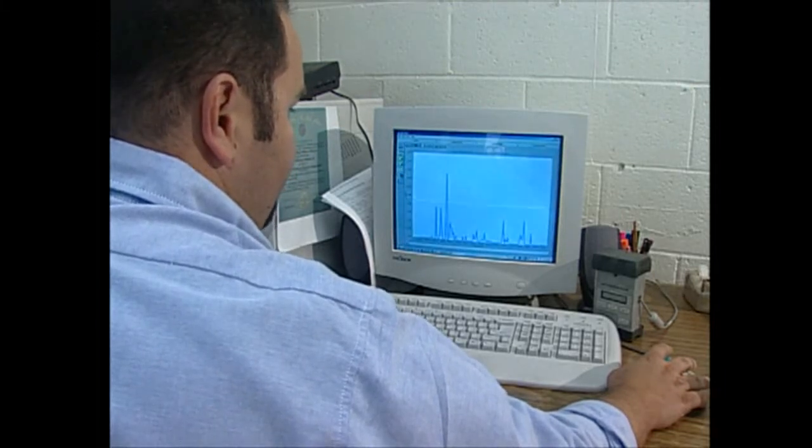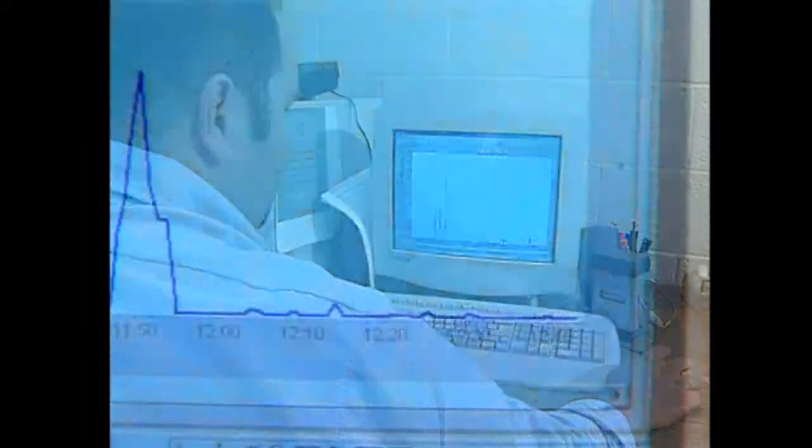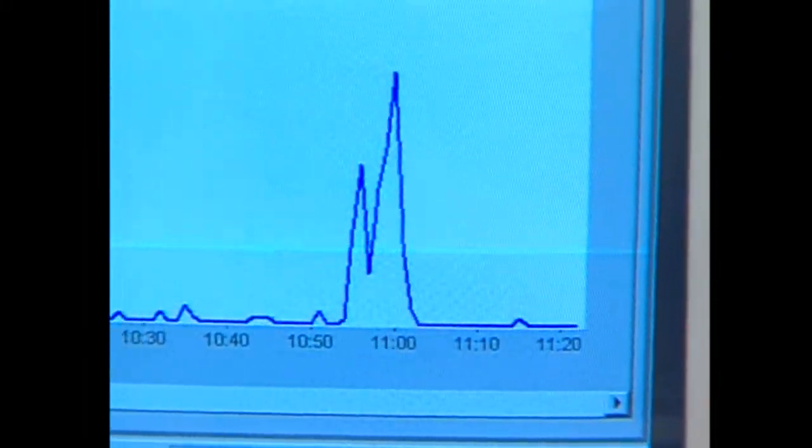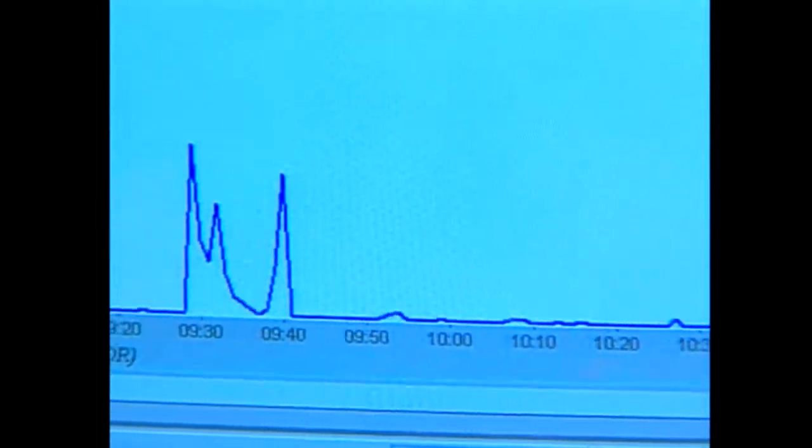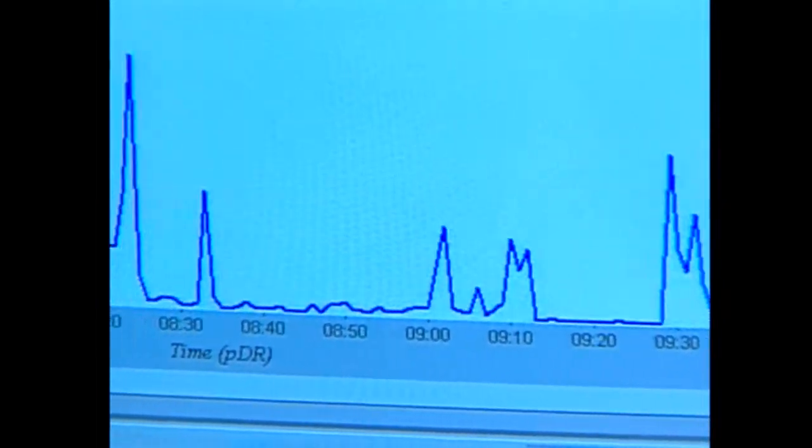The graphs show dust concentrations and changes over time. This is valuable because, for example, unusual conditions will be depicted as definite peaks on the graph. The graph will also tell you when this occurred. These meters are terrific for detective work. You think you may have a dust leak, but can't see it. This meter will help track it down in a hurry.